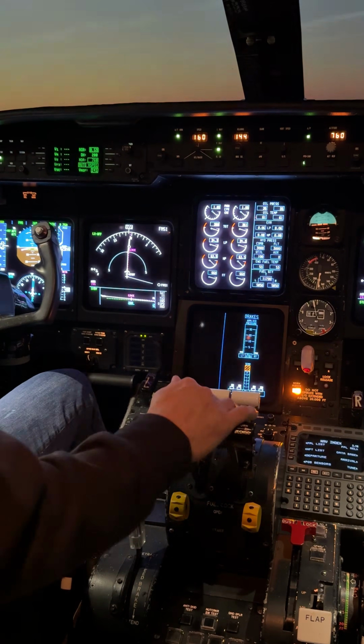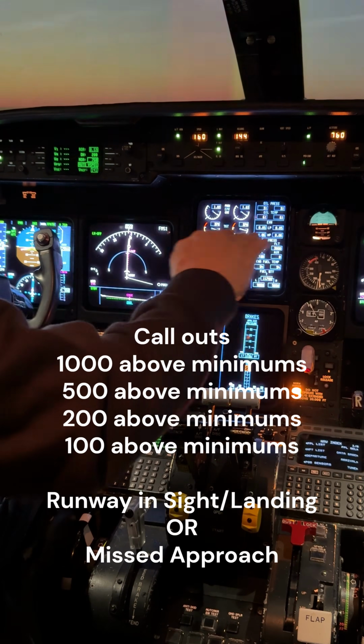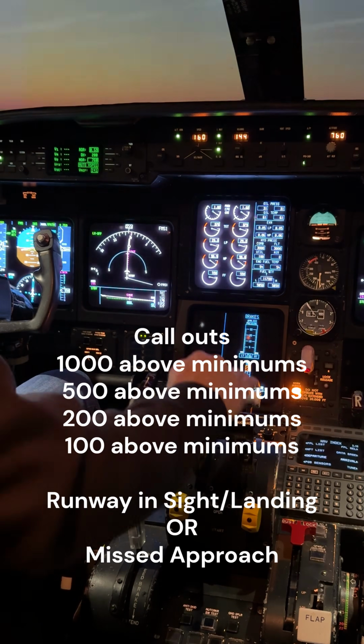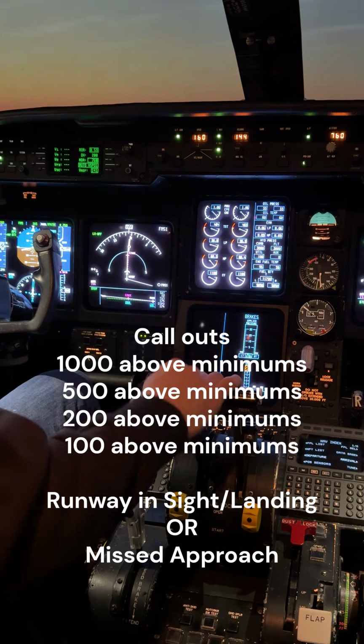And of course, standard call-outs. What are the standard call-outs? 1,000 above minimums, 500 above minimums, 200 above minimums, 100 above minimums, and then either you see the runway and you call landing or you do a missed approach.